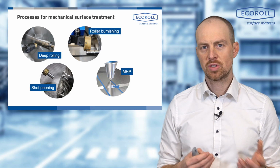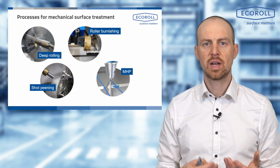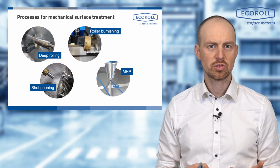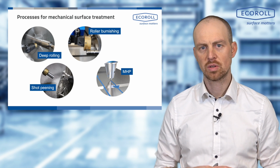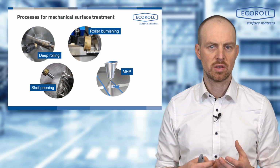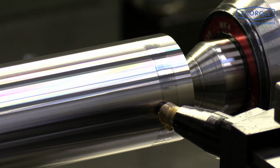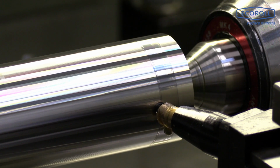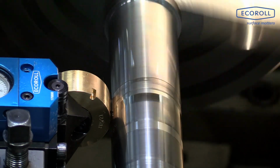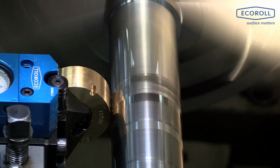One is roller burnishing and the other is deep rolling. In these 2 processes, we have continuous treatment, meaning my roller body is continuously pressed into the surface with a rolling force, rolls off this surface, and is virtually in continuous contact with the respective surface. This results in a very uniform surface texture. I often achieve textures that really resemble a mirrored surface. I achieve extremely low surface roughness and I have a very continuous and highly uniform load on my surface.